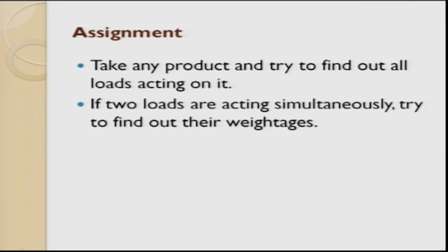The assignment for today's lecture: you can take any polymer product and try to find out what loads are acting on it. Is it only one load or multiple loads acting on it? If there are multiple loads, what weightage will you give for each load, and then you take that as a base matrix to select a polymer. Here we are not considering cost, just the loads which are applied. The loads can be tensile, compressive, shear, fatigue, whatever it is.